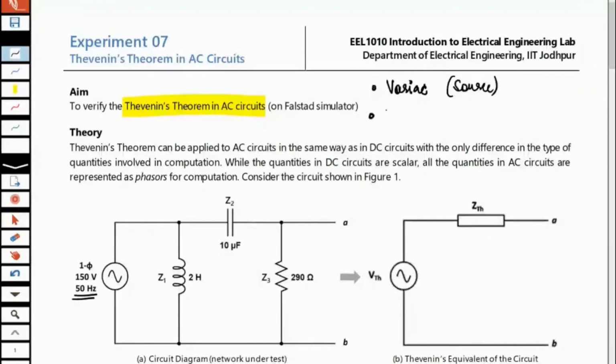Instead of using a normal resistance, we would have used a rheostat. And if you have completed the previous video on familiarization with electrical circuits, you know rheostat is nothing but variable resistance. And the one that we have in our lab, the full value is 290 ohm. If we were not using it variably, if we were using it end to end, it is 290 ohms, right?